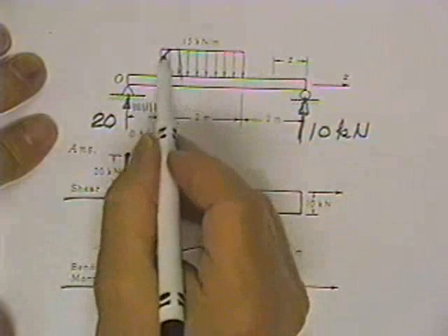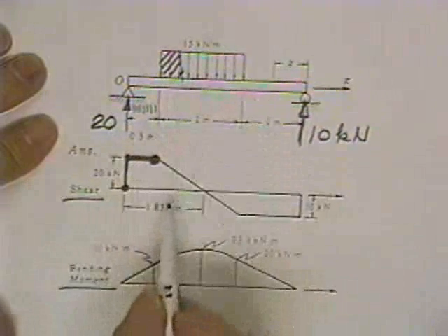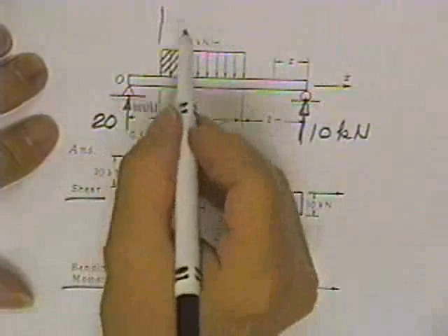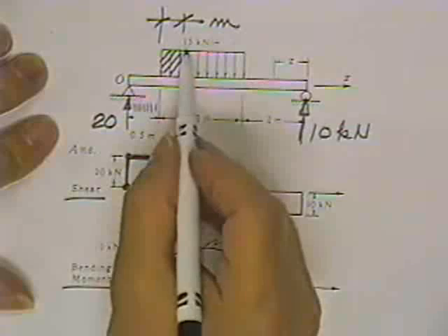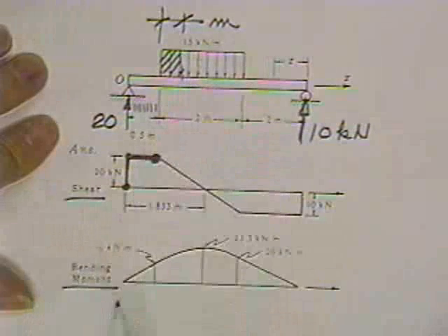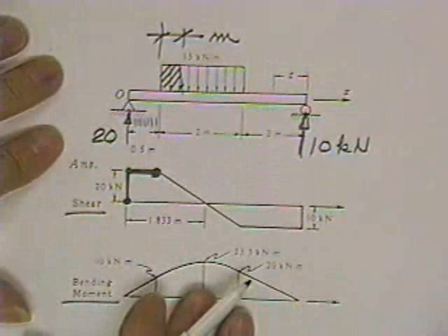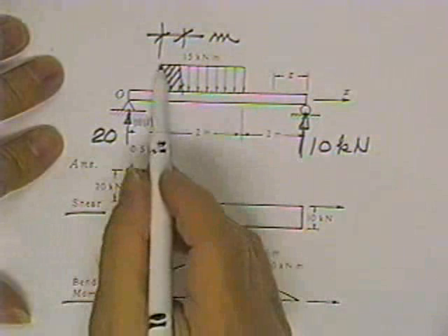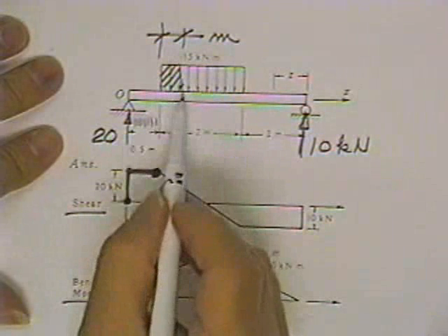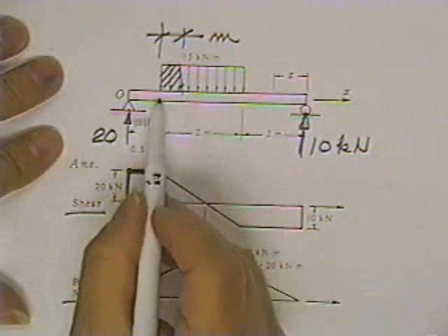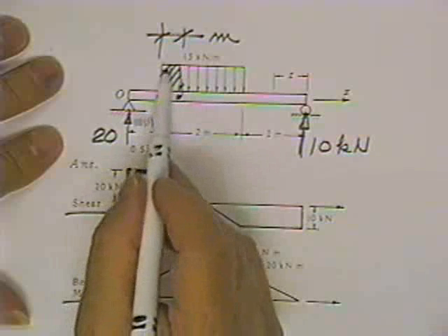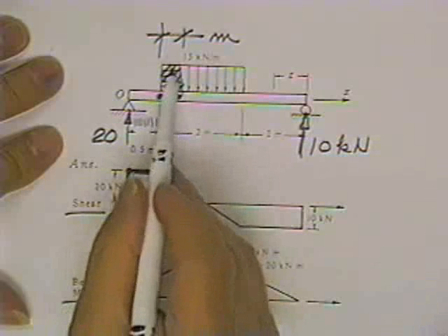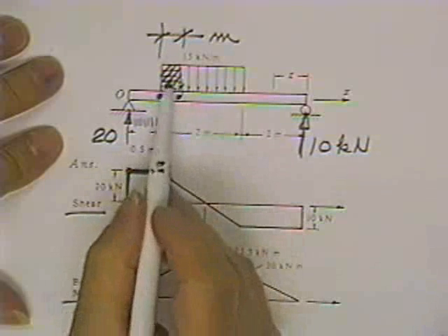Now these loads, on the other hand, are not concentrated loads. With these loads, you would have to move a whole meter before you would pick up 15 kilonewtons of load. It's like sugar bags stacked across the beam. And therefore this load doesn't say go down 15, go down 15, go down 15. It says start here, and as you move 1 meter, you will cross an area, and that area will tell you how much to go down.